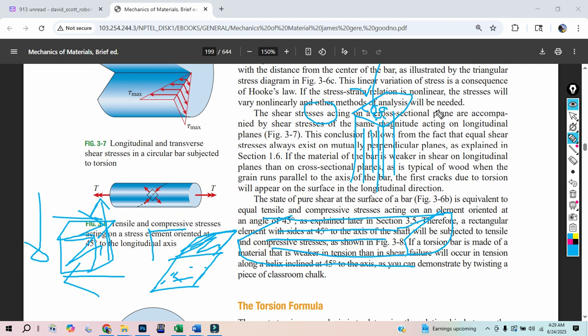If you apply a heavy weight with a base plate on it, these little soda straws will actually crush flat, so it's not very strong that way. The other way wood is not very strong, since we're going over all the ways wood's not very strong, is that these soda straws can slide past one another.